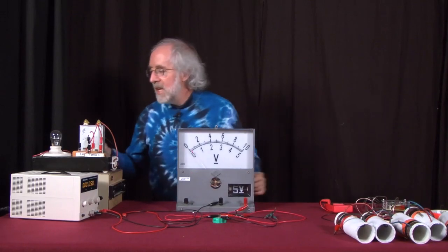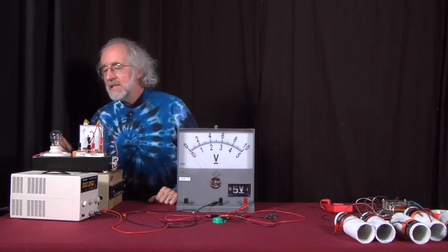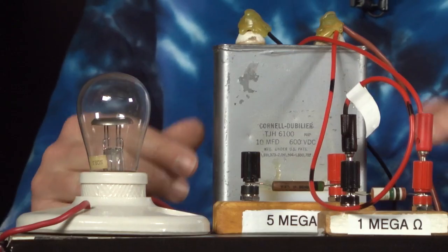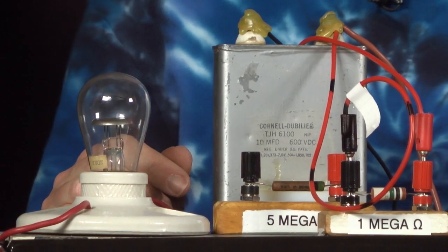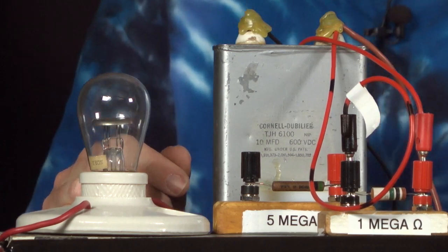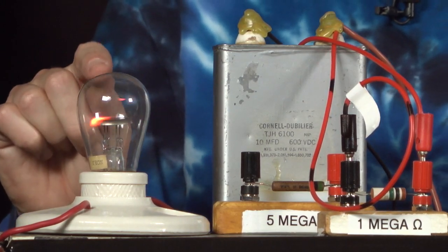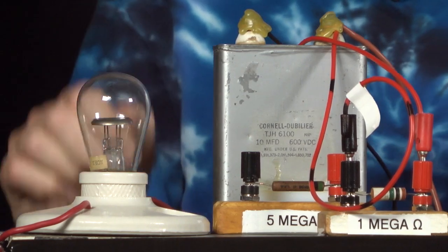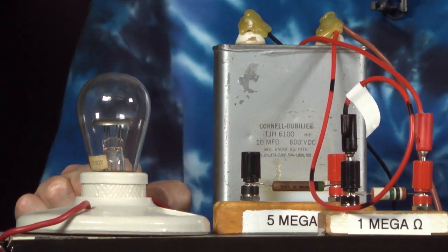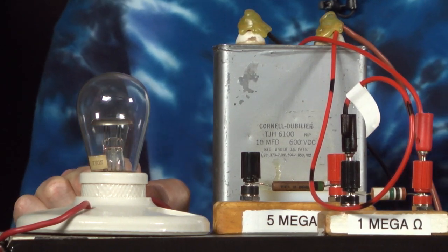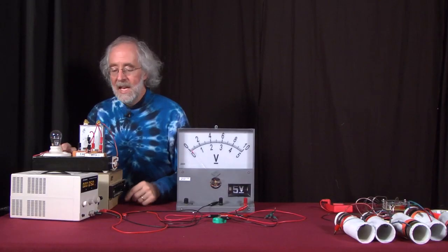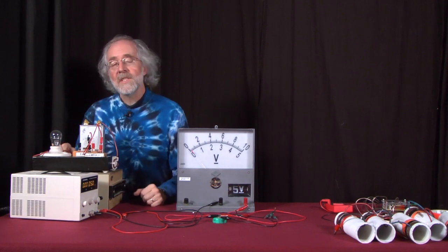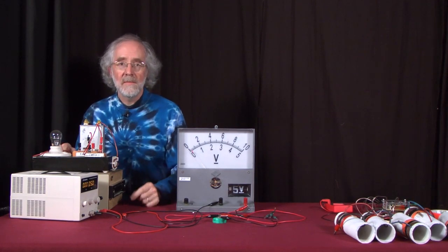Now this circuit right here is a little neon light bulb flasher, and what happens is this. There's a capacitor that charges up through a resistor, and as it charges up, it reaches a certain voltage. When the voltage is big enough, the neon light bulb lights. But then that discharges the capacitor. Then the process starts again, and the capacitor has to charge back up again, and it's charged through a resistor. So it's an RC circuit, but it's an RC circuit for charging.